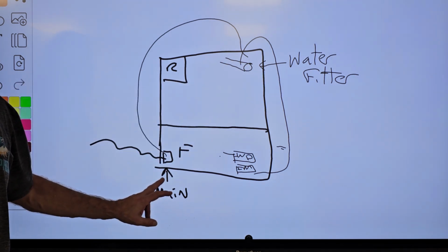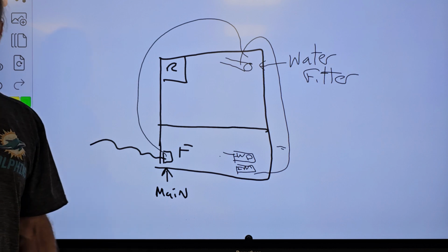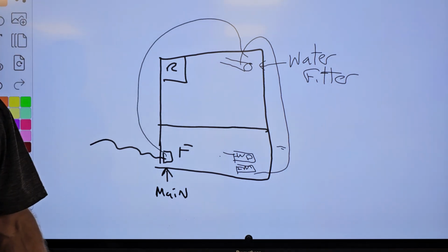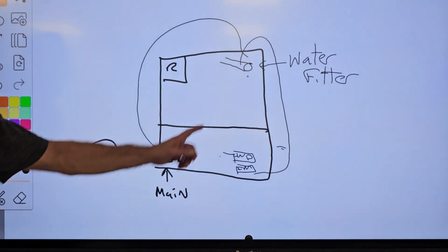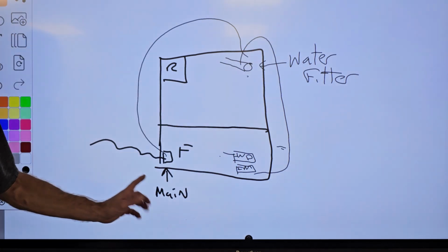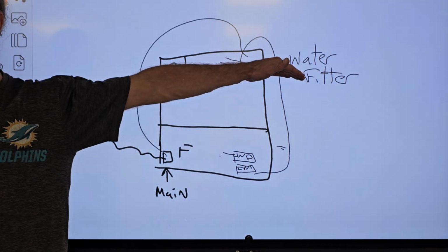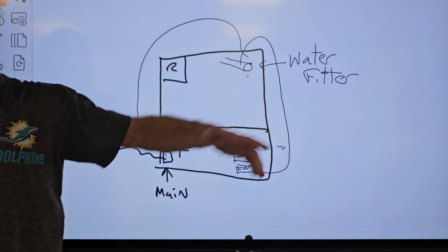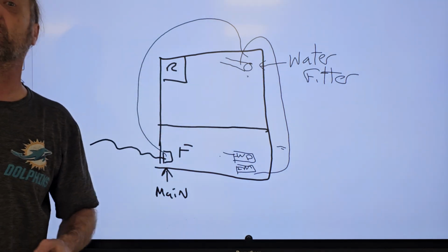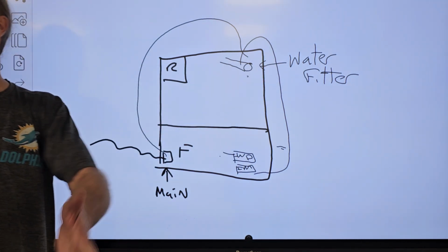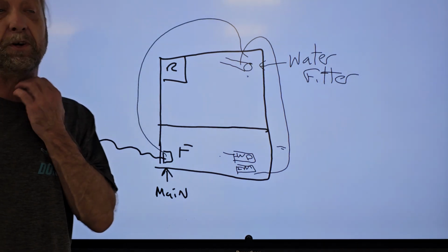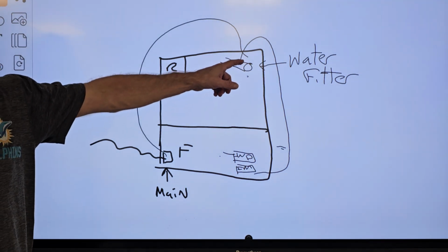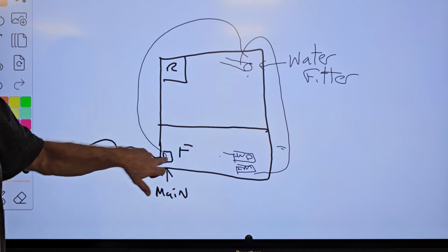The reason why they have the additional valve is so when the ice maker or you're not calling for water, you could just pull that valve out and pull the filter out, because this valve will stop the water pressure from going through the filter. Because remember, if it was behind the fridge, you had to turn the water off to change it. And then when you turn it back on, that valve leaks, or it leaks behind the fridge. In this case here, when you pull it out, that does that.